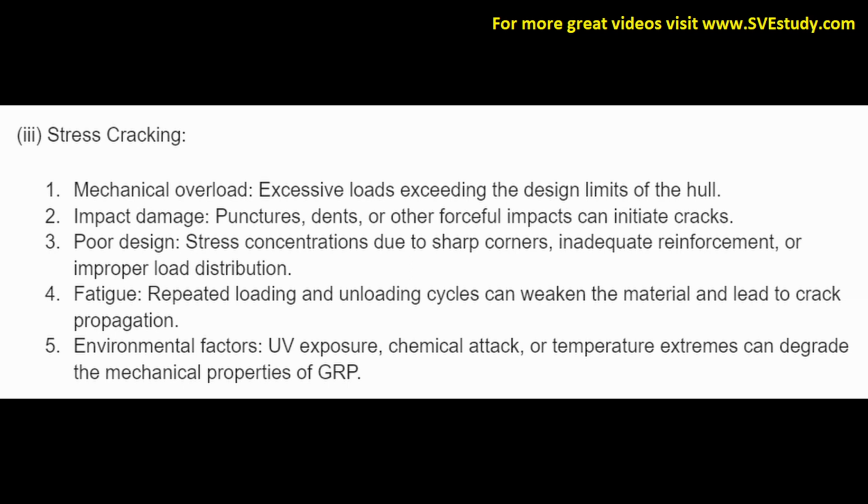3. Stress cracking. 1. Mechanical overload. Excessive loads exceeding the design limits of the hull. 2. Impact damage. Punctures, dents or other forceful impacts can initiate cracks. 3. Poor design. Stress concentrations due to sharp corners, inadequate reinforcement or improper load distribution.